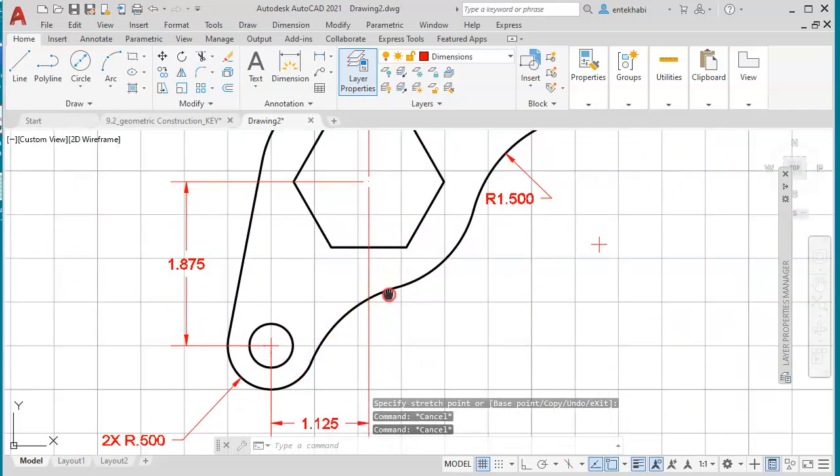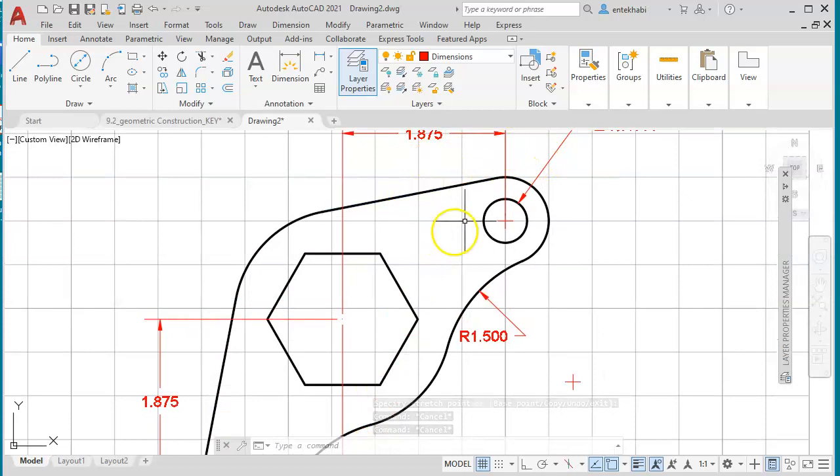And we do have a horizontal location for this in the X direction. We don't have the Y direction, so we need to add that one too. And notice that I don't have any center line yet because I have not added the radius for this. If I add the radius, it's going to automatically give me one. So let's do that one too, add in the radius dimension.